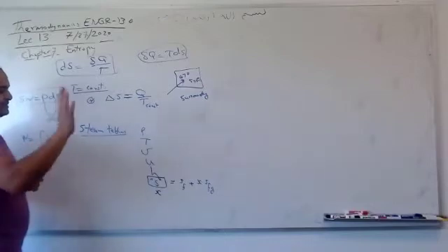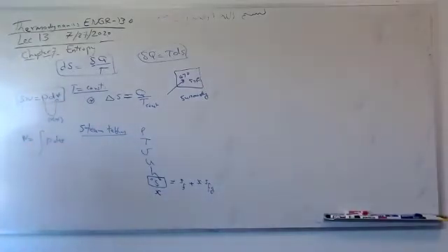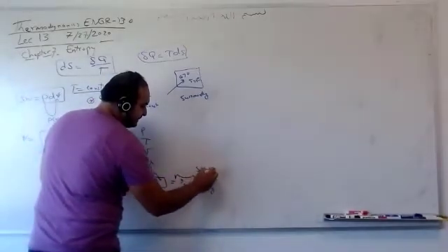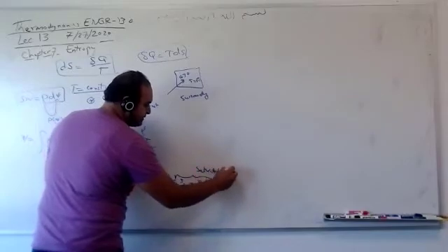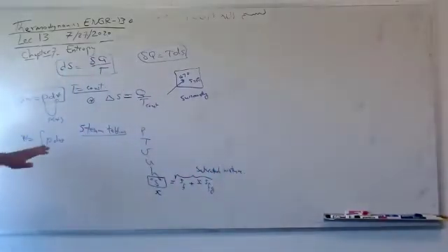If it's superheated, it's a direct output. You can know it exactly. If it's superheated, just s equals s in the superheated table. So this is only for a saturated mixture. We gave some examples for that. So today we're going to continue. We stopped at the steam table. Today we're going to continue with that by using other things.